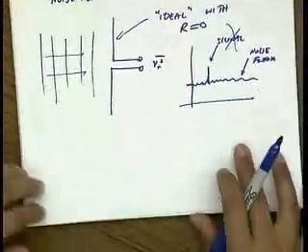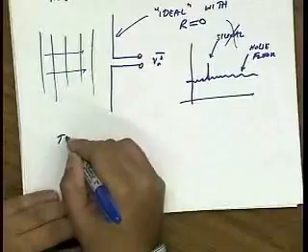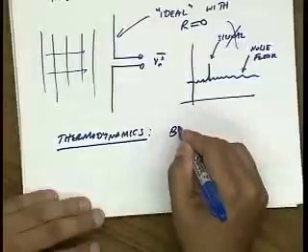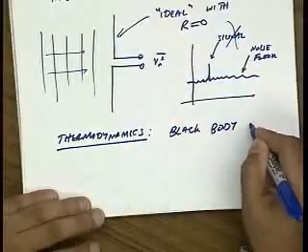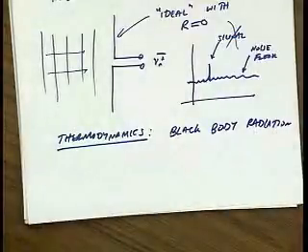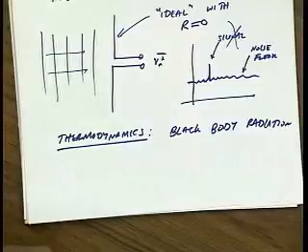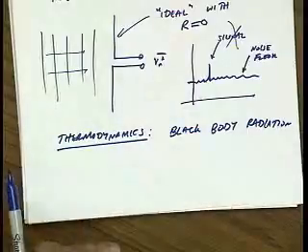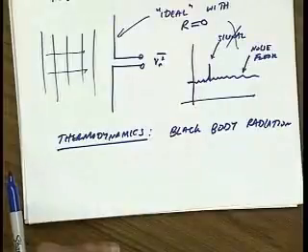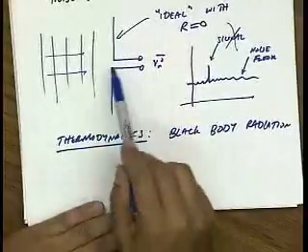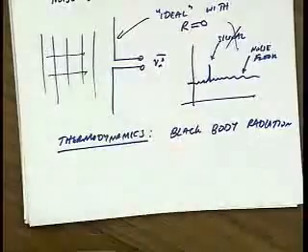Well, I think you guys probably know the answer. You studied this in thermodynamics. In thermodynamics, we learned about black body radiation. You know that any body at temperature T radiates, and that's called black body radiation. So depending on where I point this antenna, if I point it to the sky versus the ground, which is pretty warm, I'll pick up more radiation coming off the ground. So the important point is that even though there's nothing actually generating noise within the circuit, there are no resistances here, this antenna still can pick up noise.